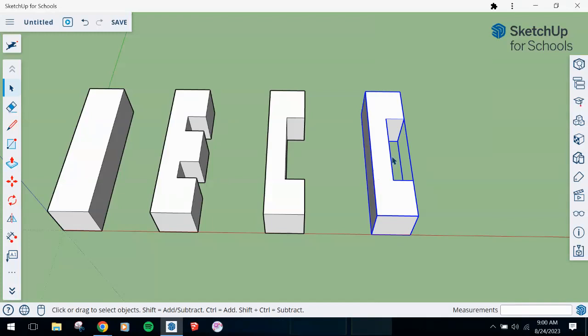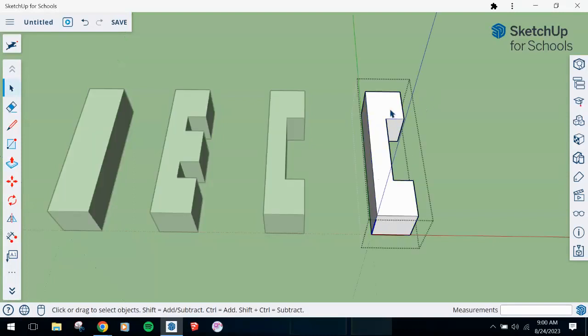So the measurement that you're given is 1 1/8 of an inch. So let's double click. Let's use the tape measure tool. And we're going to come down here from, oh, did I click in the wrong spot? Yes, I did. If you click in the wrong spot, like in a corner, the best way to get out of this is to press escape. Don't make a second click because you'll end up making a guide point where you don't want. So make sure that you've got this red square before you click, and then come down here 1 1/8. So to type 1 1/8, you're going to type 1 and then use the space bar to put a space in between your whole number and your fraction. And if you look in the bottom right corner, you'll see where it says length 1 space 1/8. That's 1 1/8. So once you've got that, press enter.